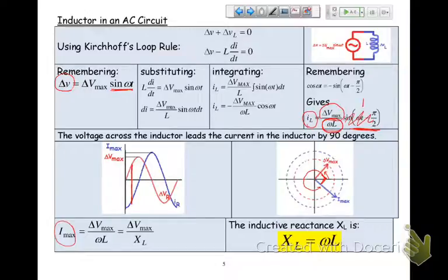Well, I used to say that I is equal to V over R for a resistor, and this is I is equal to V over omega L. So by analogy, let's just say that this omega L acts like a resistor. I don't want to call it a resistor because it's not a resistor. It's an inductor, so I'll call it my impedance, my reactance. I'm sorry, I get those words mixed up all the time. Reactance. And it's given the symbol X, but it's got units of ohms.